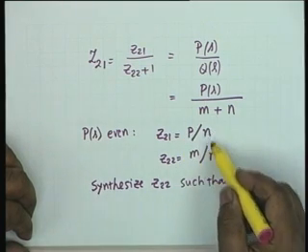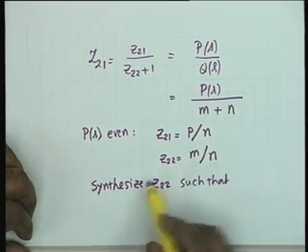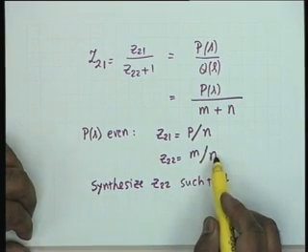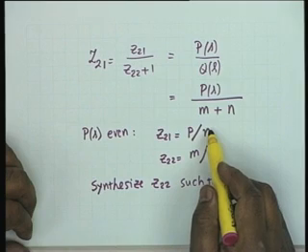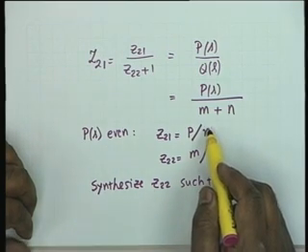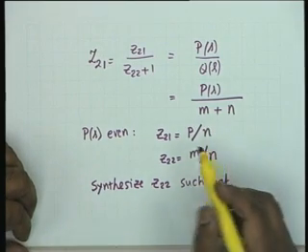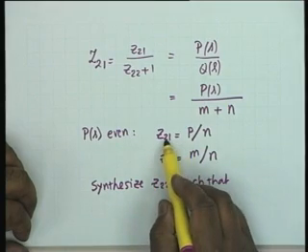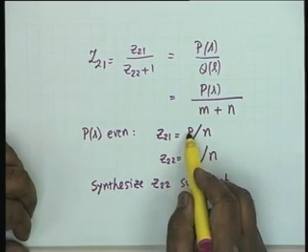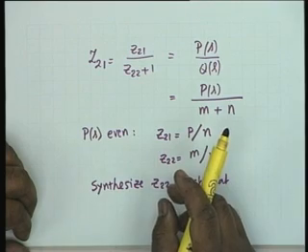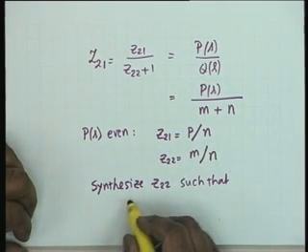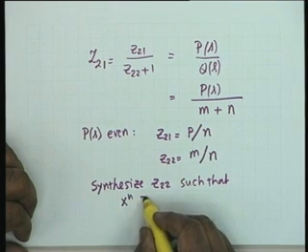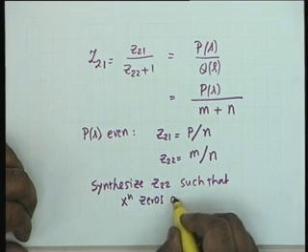They have the same poles, N. Realizing Z22 shall mean that we have also realized the poles of Z21. The only care we have to exercise is to see that the zeros of Z21, which are the zeros of P, which are in turn the transmission zeros of the network, are realized.